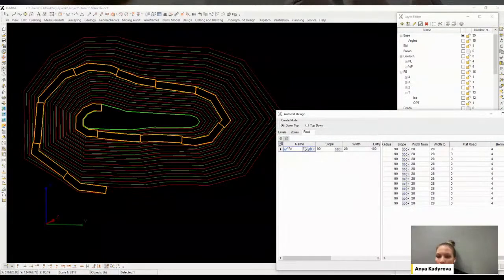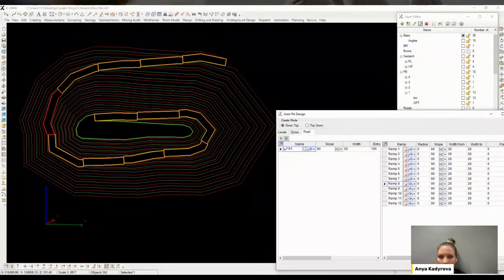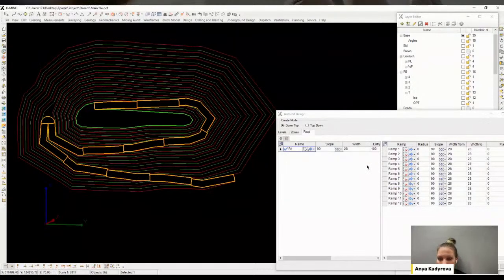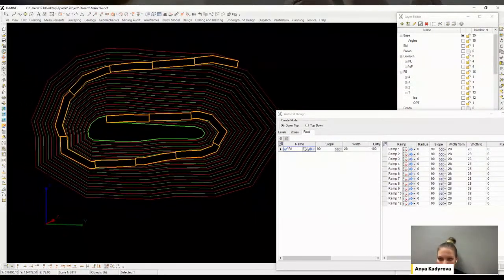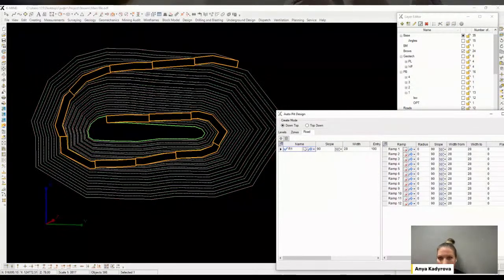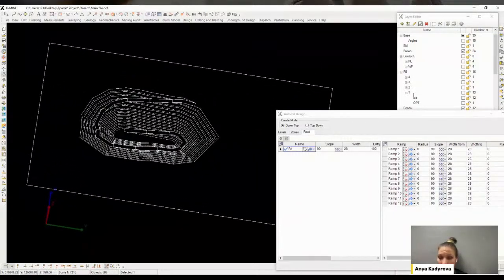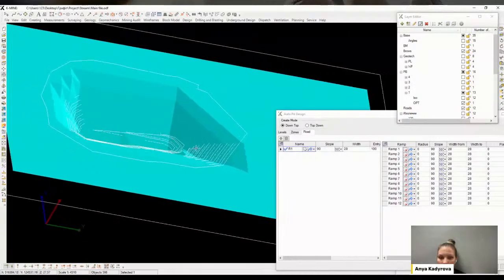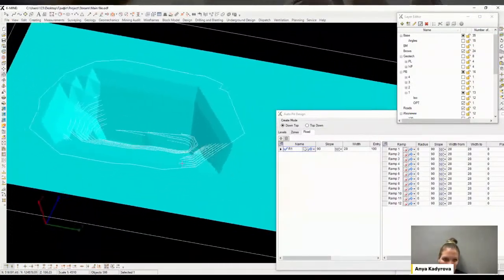So in the process of automatic design, both one and several baselines can take part. Also, different slope regions can be used to define unique parameters for pit areas. With the help of the layer editor and the property editor, it's possible to place the necessary elements in the right place. It's highly recommended to keep the file structure in order so you can quickly access all of its elements.